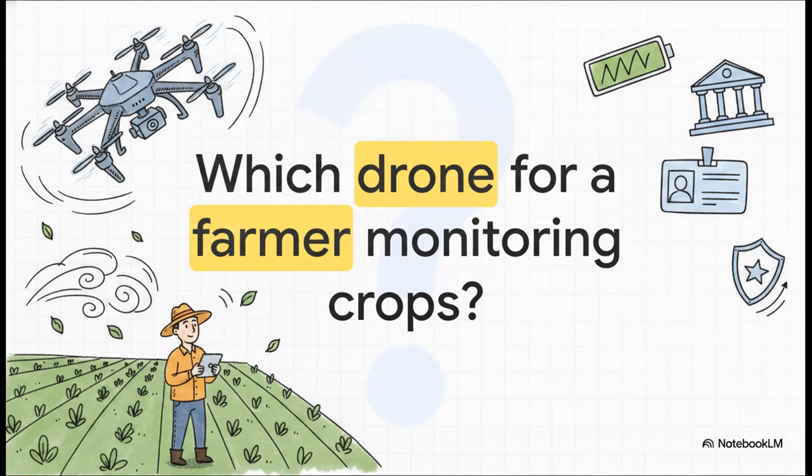Let's apply all this to a real-world scenario. Imagine a farmer needs a drone to monitor crops across a massive property. Based on what we've learned, what do they need? Well, they'd probably want a smaller medium-class drone, maybe a hexacopter so it can handle the harsh winds out in the open fields. It needs a high-capacity battery for long flights and a specialized multispectral camera. And because it's for an agricultural business, it falls strictly under commercial regulations. So CAA registration and official pilot certification are an absolute must.